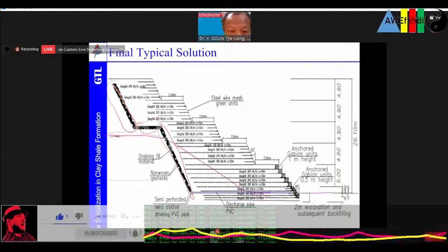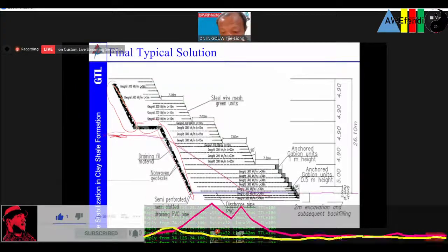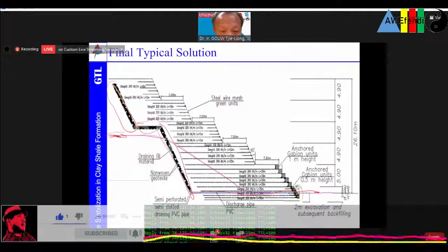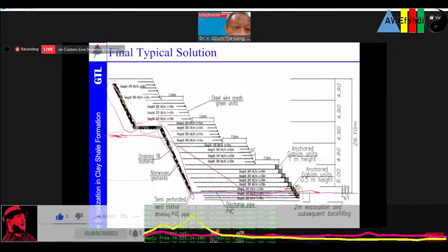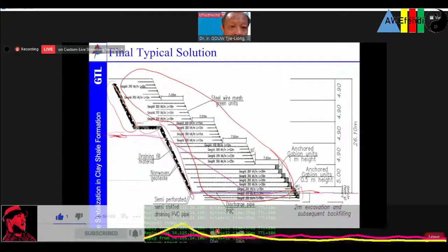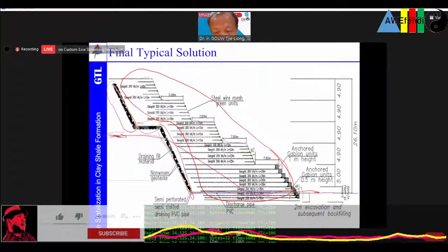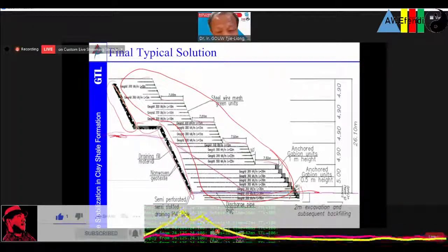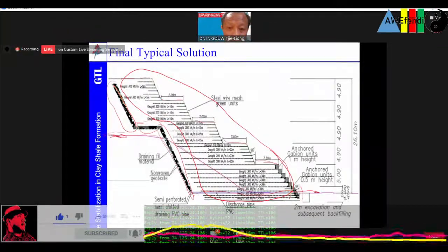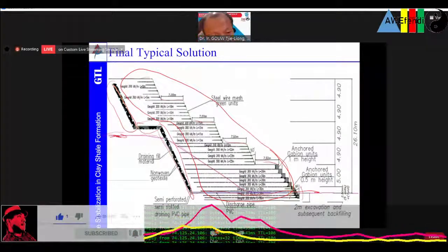Then we cut that and make the drainage over here, then the discharge pipe over there, to bring the water out if there is any seepage, to prevent saturation. On the top, we also cover it with grass soil, so that limited water will seep through the system, so as not to reduce the strength of the backfill material over here, to prevent it from saturation.